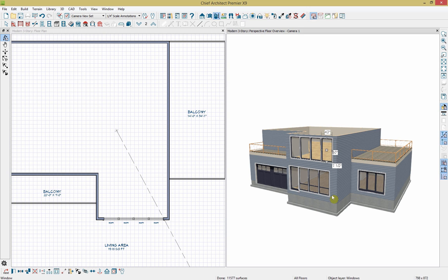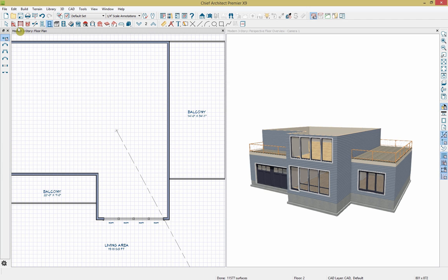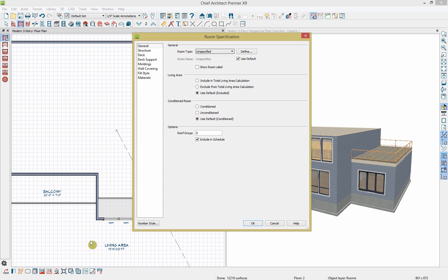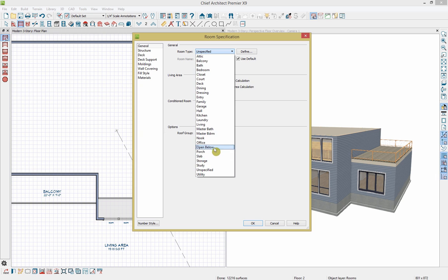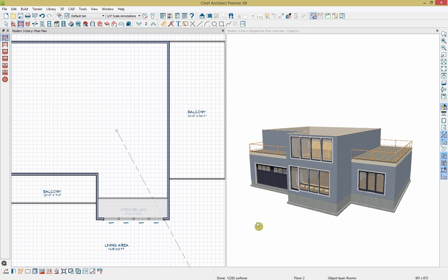And in this view, I can see that that first floor is pretty dark. So I want to bring some of the light that might be coming in from our second story into that first. So we're going to create kind of a loft feel just by going right back up to our railing tool. I can just click and create a railing, open up this little space that we've created, and change the room type on that to be open below. And in our 3D view, you'll see how we now have additional light coming down through that opening, kind of creating a nice effect there.